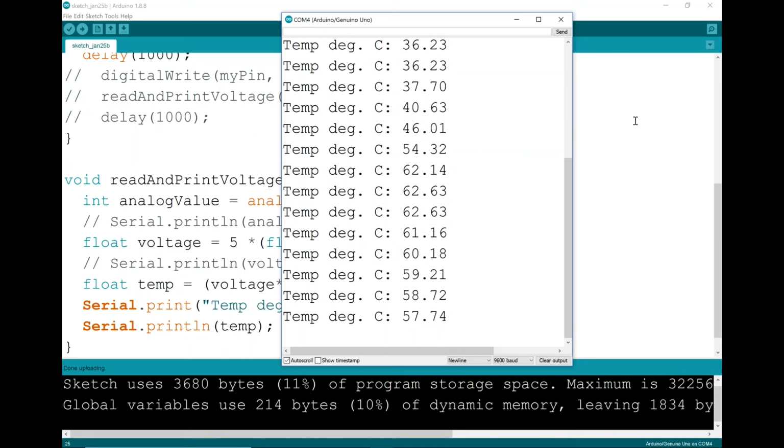All right, but my temperature sensor is working, and I've converted what it's, let me emphasize this again. The temperature sensor is a device where the temperature in the room, the temperature of the device, influences how much voltage it utilizes. So the actual signal that's being sent to the microcontroller is not temperature, but voltage. And then in my sketch, I convert that voltage back into a temperature because I understand how the temperature sensor works. I know that it consumes a voltage proportional to temperature in Kelvin. So I can go back and forth.